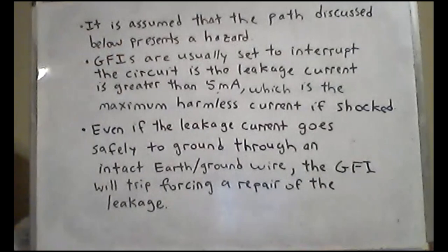And so the 3-wire system, the safety case that goes around the appliance, grounding the safety case, grounding the neutral wire, all of these are safety features. On top of that, in cases like the bathroom or kitchen areas, having GFIs, ground fault interrupters, is yet another safety feature that tries to prevent shocks.